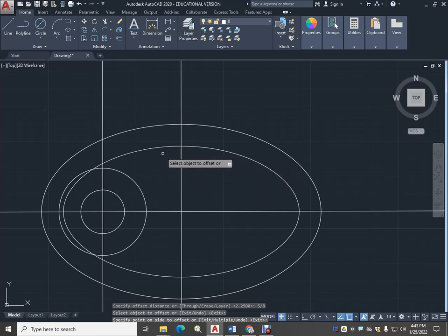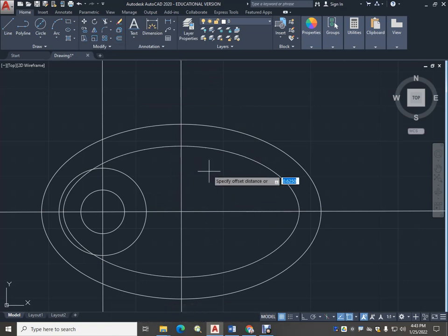So this is the outer edge of the hole, and now we're going to come back in, and now we have a center post coming down the center, and that is also 5/8, but we want to do half of that on either side, to get a total distance of 5/8. So half of 5/8 is 5/16. All you have to do is double the bottom number.